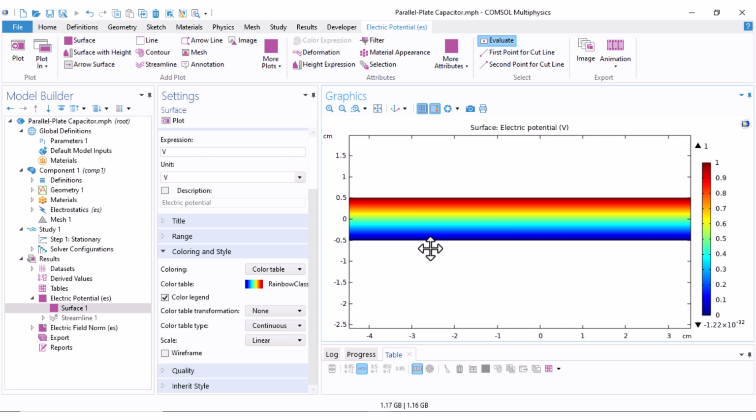This is a very important point. You set some boundary conditions, set some physics for your model, and the software will calculate the output. You as an engineer should have the knowledge to analyze your output, to find out if your output is correct or wrong. This step is called validation. If you cannot validate your simulation, it has no value. A validated simulation can work. Okay, here I know that I have set here 0 volt and set 1 volt. Check number 1. Okay, it is correct. We should move from 0 volt to 1.